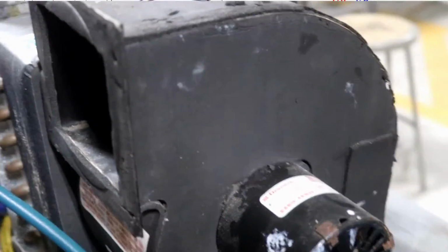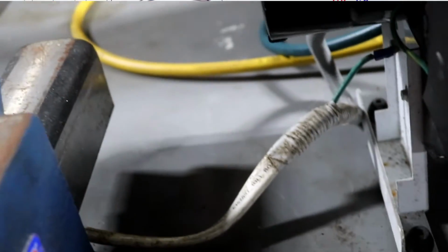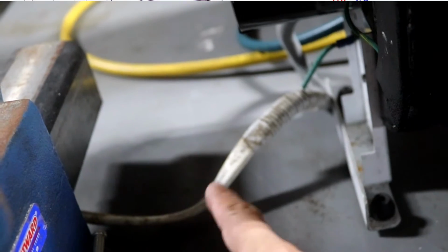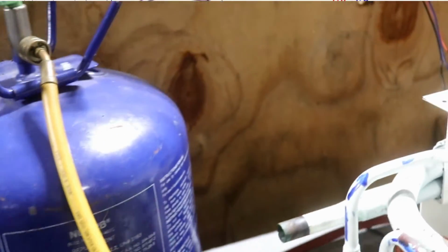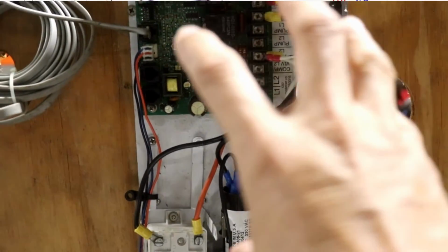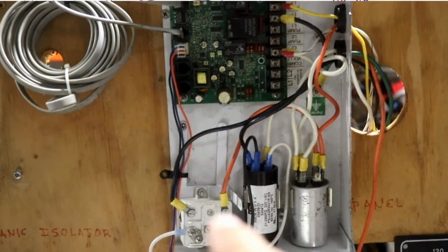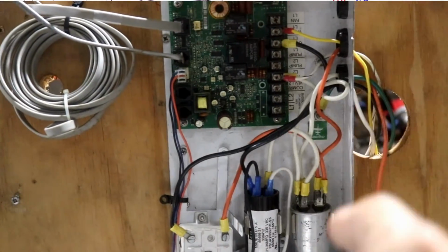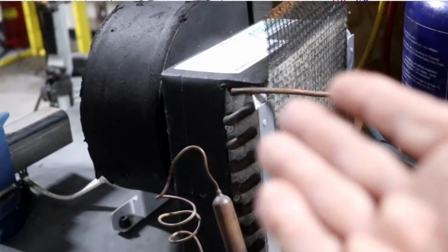This is the operation of the blower, and of course the blower is activated with 120 to 140 volts, and that voltage is coming from the central control box that I am going to explain in the next episode. How is the wiring of that central control box? Okay, this is the evaporator.